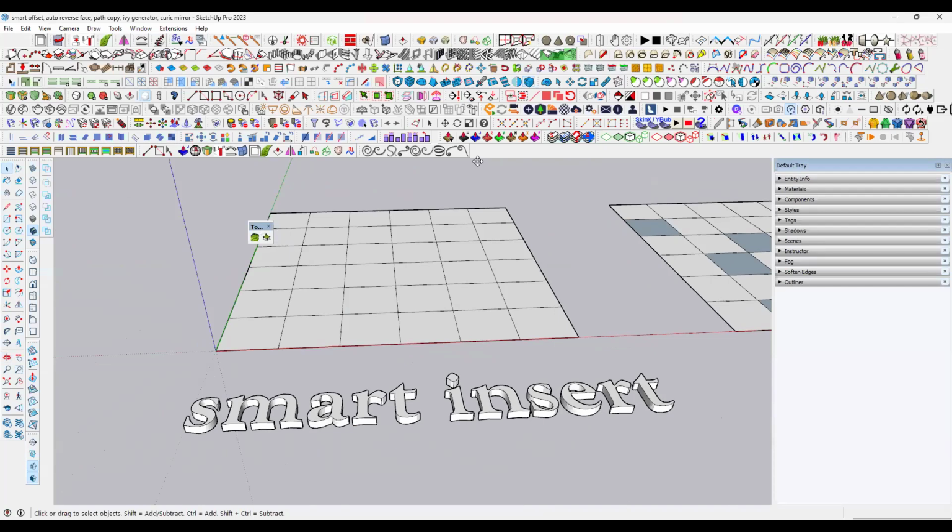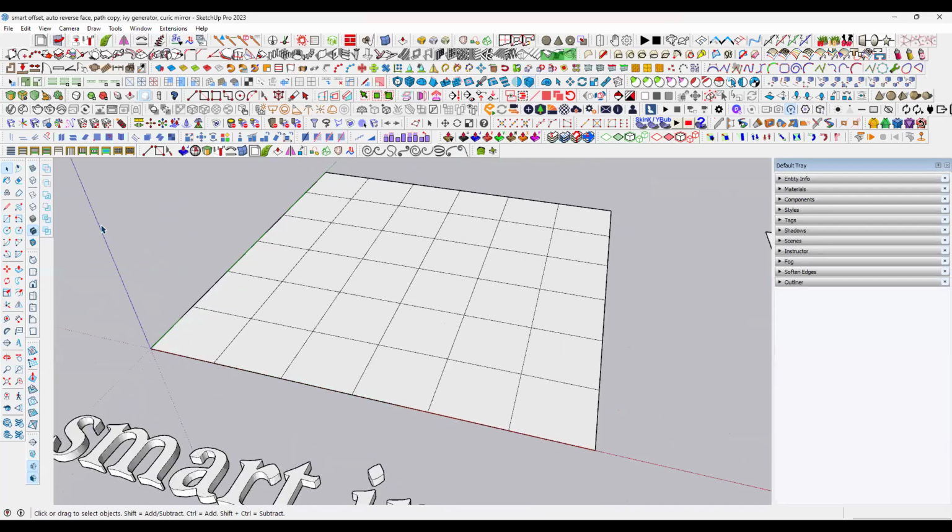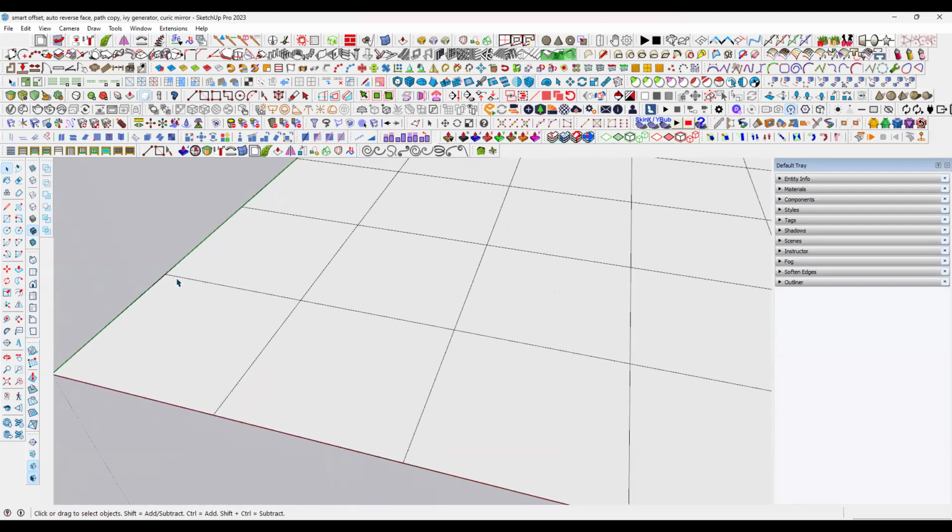And see, here I want to first explain the smart offset. So what is the meaning of smart offset here? See, when you are creating tiles, whenever you are going to be creating tiles, it is very helpful, because I've seen most of the students when we are applying the offset for this one. So generally, let us assume these are the tiles in the kitchen, or maybe tiles in the toilet, or maybe the tiles in the elevation. Generally, for each tile, we have to give some gap in between them. In that situation, I have seen we are most of the time using this kind of an offset.